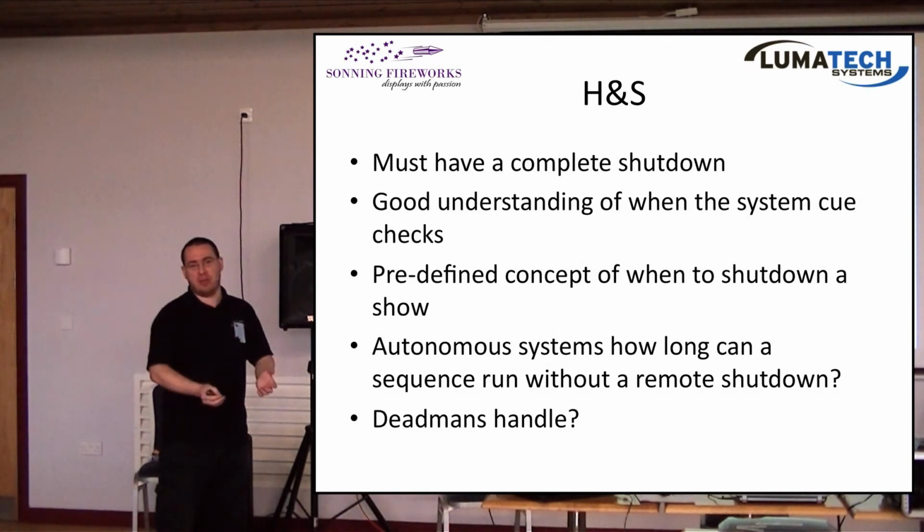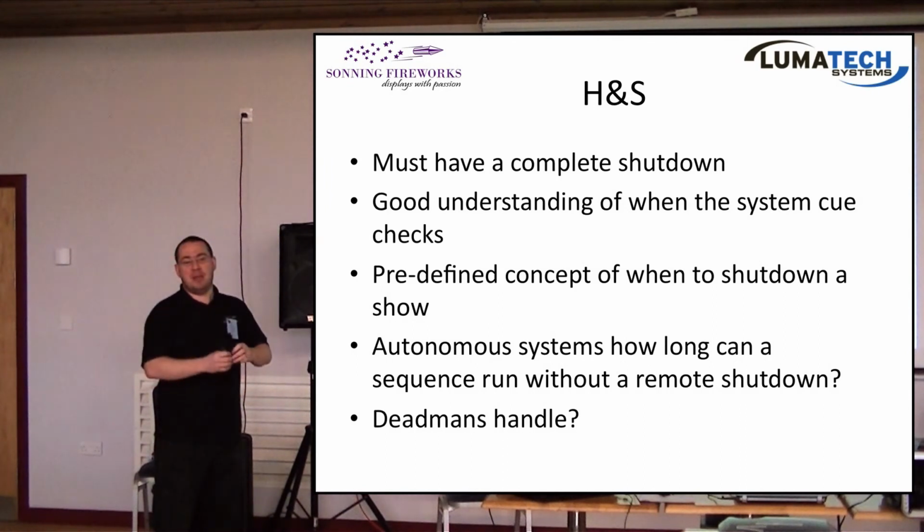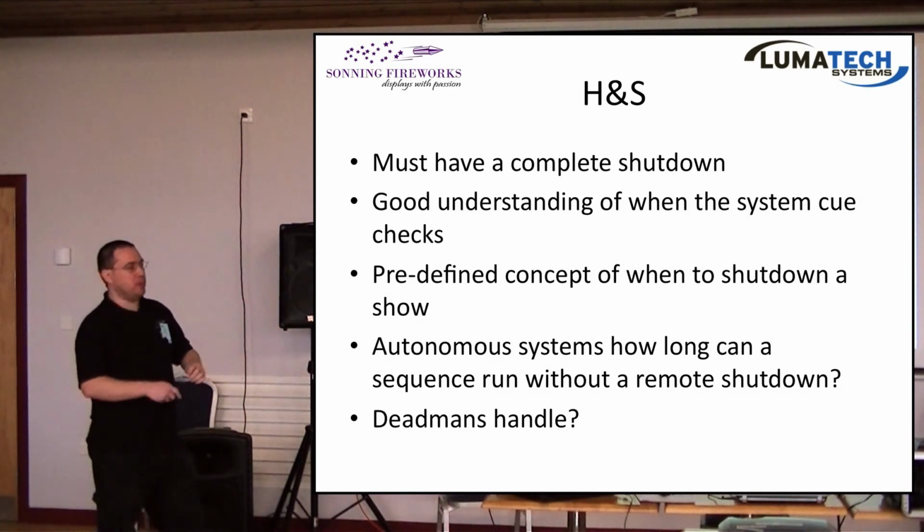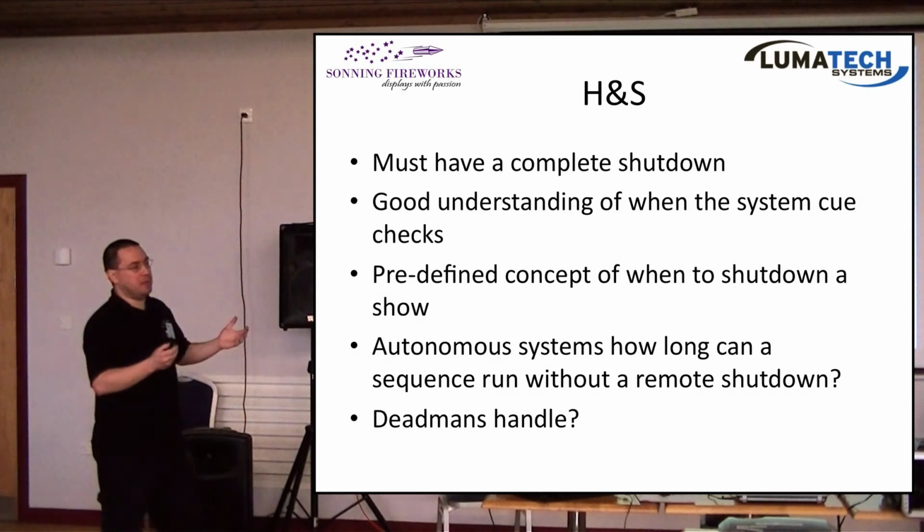It's putting very low current through. But if there's a fault on the module, potentially at that point, you could have an issue. So certainly when we're Q checking any system, we always make sure there's nobody near any of the products while we're doing it, because that is a point where things can go wrong with any system.